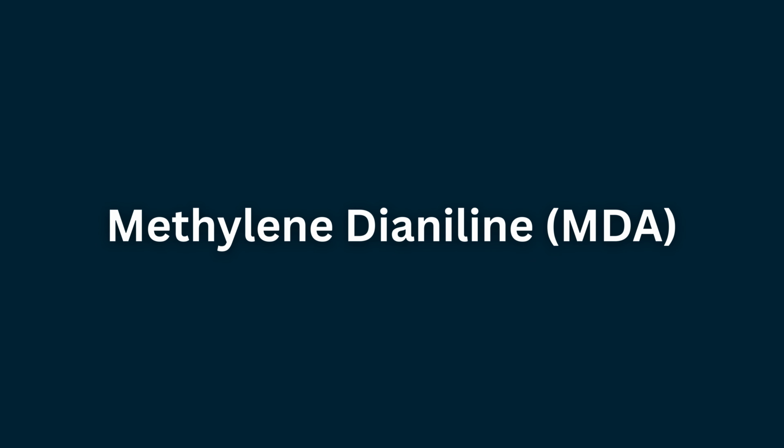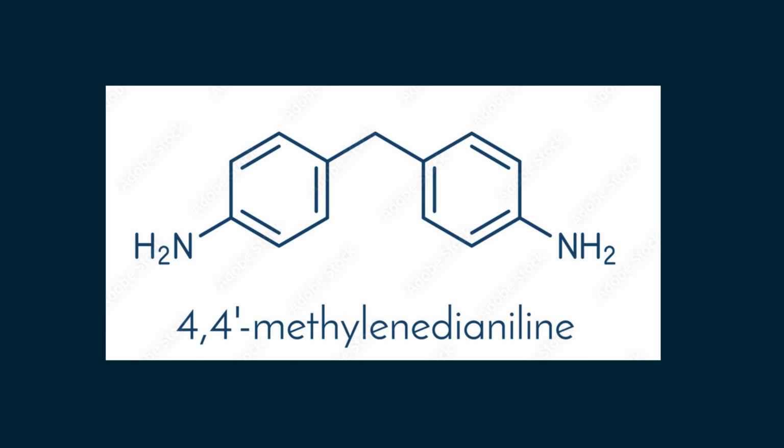Methylene Dianiline, MDA. Methylene dianiline is another aromatic diamine used as an epoxy curing agent. Like MPDA, it is a solid compound but has a higher melting point, around 90 degrees Celsius. Its low polarity and processing difficulties limit its use in many adhesive formulations.